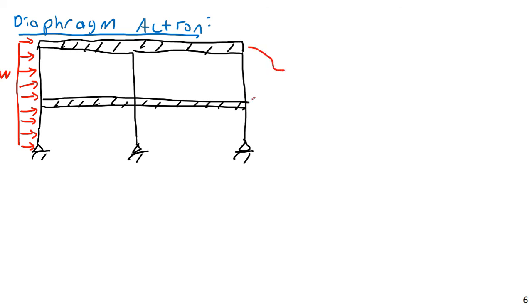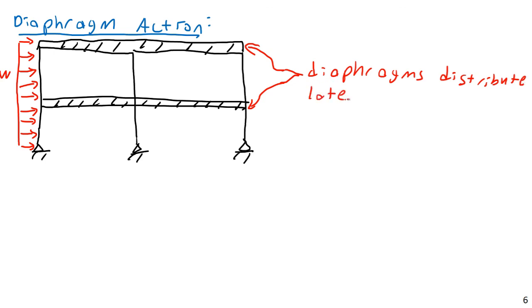And we call these things, and they don't necessarily have to be slabs, they could be a very strong structural frame, etc. But we call this thing a diaphragm, especially if you have a rigid diaphragm. Diaphragms distribute lateral loads to columns. That is their function. Well, also actually, hold up the live load and dead load and the people and everything else.